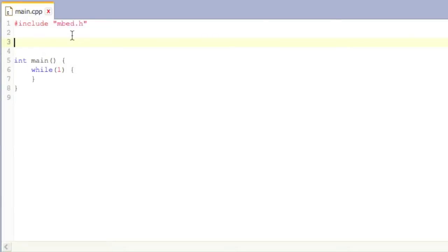But with this, to use the digital to analog converter, we're going to use a class called AnalogOut. What this does is instantiate one of the digital to analog converters on your microcontroller. The way that it works is you first name it something. We're going to call it DAC, and you have to assign it the correct pin. In this case, the only digital to analog converter on the KL25Z is the PTE30. We assign that PTE30 as the digital to analog converter.